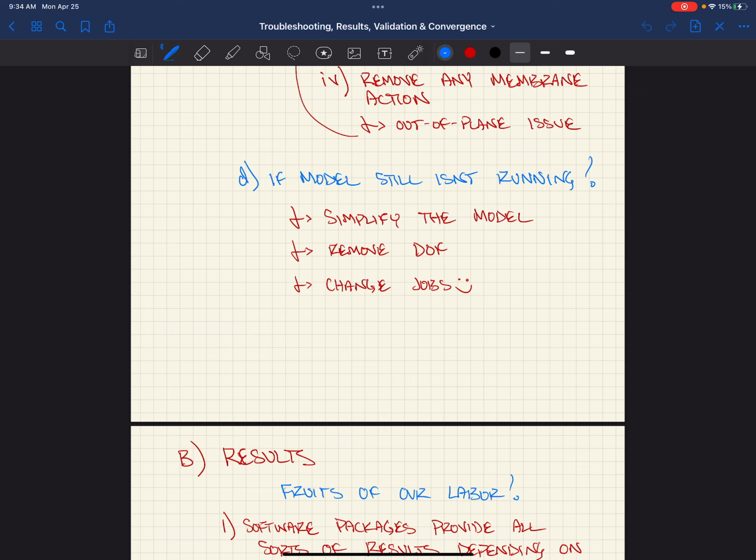So what version of VA are you running? This is 19. Why can I still not find the offset box for my plates? I couldn't find it either. So you offset the member, not the plates. Oh, that's why. Yeah, okay. There it is. You offset the member, not the plates.